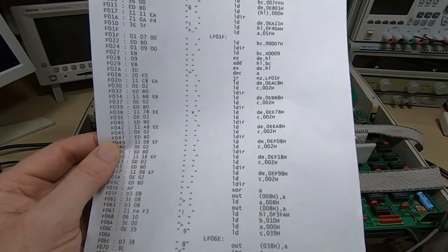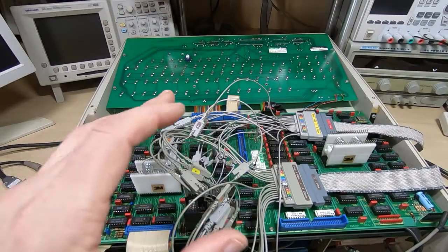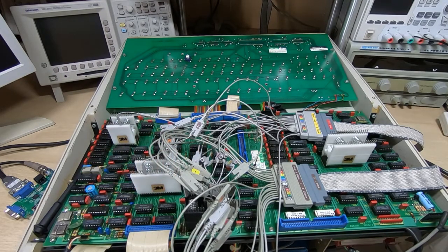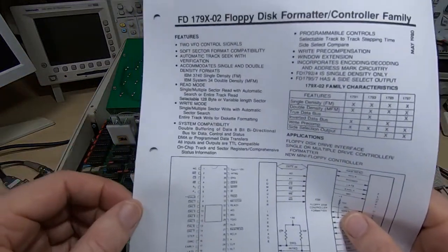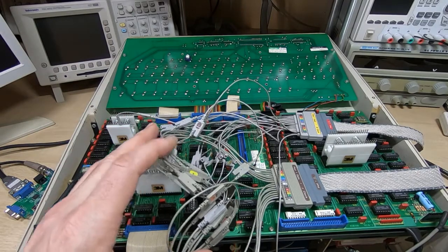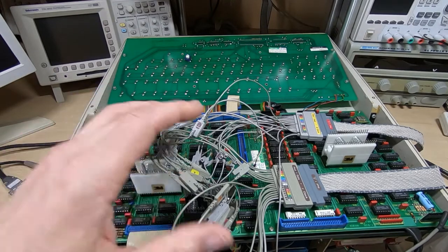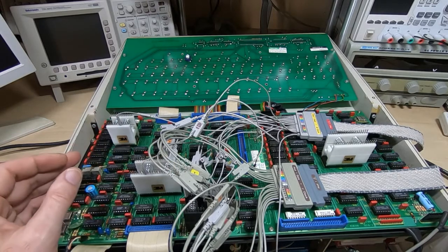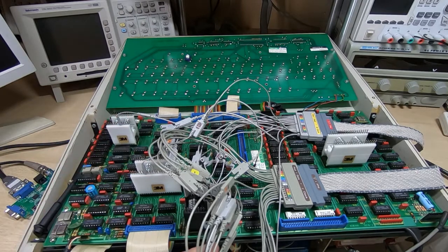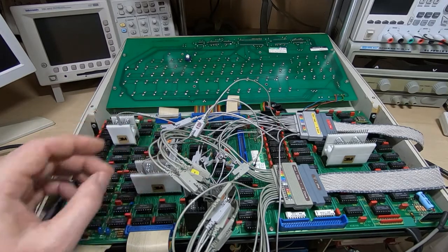So what I've been doing is going through this, figuring out the best way to approach this particular problem. We are most interested in the floppy drive controller chip, and we looked at the spec sheet for this, and there's a table with 4 addresses, and those 4 addresses are for the 4 registers that we need to be able to access within the device. What we need to do is find out what address in the system they're mapped to. There are many ways we could go about doing this, but I'll boot up the logic analyzer and show you the way that I've got this configured to detect what address those registers are mapped to.